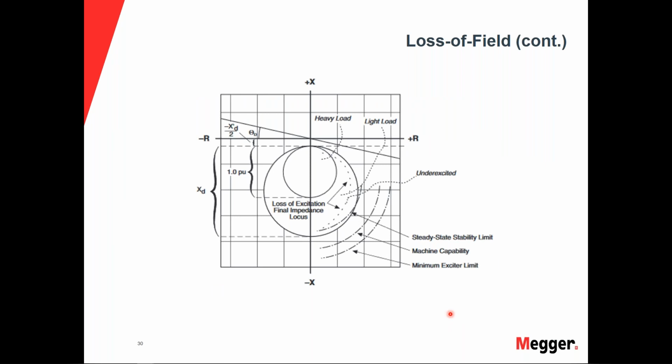In the electromechanical world, there are many electromechanical relays that are used for the setup. And in the microprocessor world, of course, we only have one that can actually handle multiple elements at a time. So usually when you're testing a loss of field, or a 40 relay, sometimes there are a couple of relays involved with that. We'll have to test the timer. We'll also have to test the relay itself and make sure everything is working properly together.